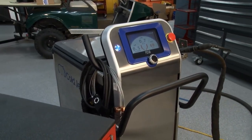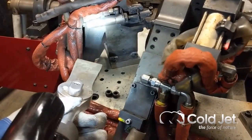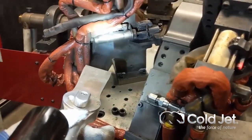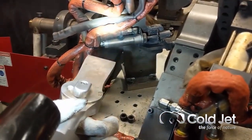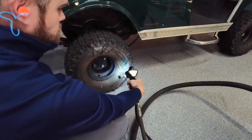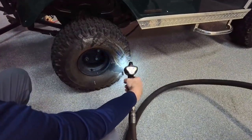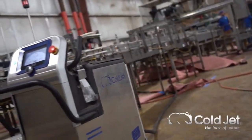There's two main benefits to it. Number one is it's not abrasive. It's a very soft material, so as you blast on all sorts of different surfaces, metal, plastics, rubber, it's not going to damage them. And the second part is there's no secondary waste. So that dry ice impacts the surface, it sublimates from a solid state to a gas state and leaves no residue left behind.